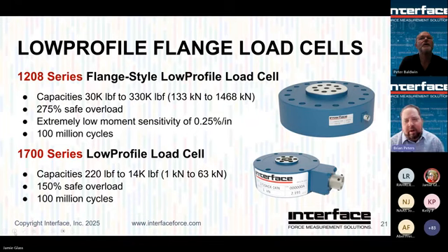We offer other pancake style solutions, low profile solutions that are also fatigue rated. Again, fatigue rated, 100 million fully reverse cycles. So two more to highlight here are going to be our 1208 series and our 1700 series. Both of these are, I would say, more popular in the European market, but they're still great choices, partly due to the ease of assembly. So the 1208 looks very similar to the 1000 series you saw earlier. However, it incorporates a multiple bolt pattern center flange. It's recessed on the bottom, so you can actually put cap screws up through that and attach specifically to actuators.